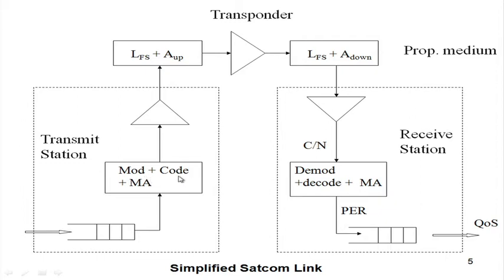This code is for error correction coding, not the baseband coding. We will discuss multiple access and other things later. Just take this word, that multiple users are accessing. In this case I have drawn only one user, so they have to share the transponder. That is why it is called multiple access, the sharing business is there.